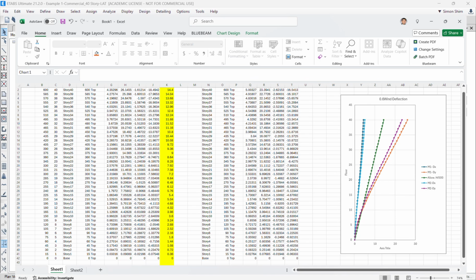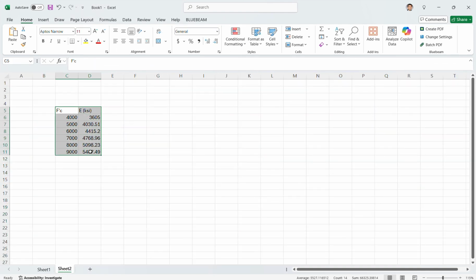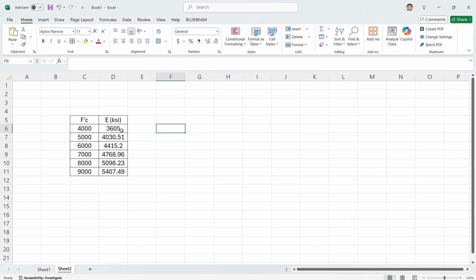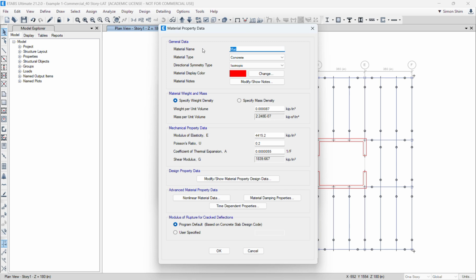Today I showed you this formula basically, right? You could calculate it, you can type in this, but this is in KSI, right? Young's modulus, normal weight concrete, you can calculate 57 times the square root of f prime c, right? So it varies among the concrete strengths. So I create a 6,000 here. I'm going to create a few more, 7,000.